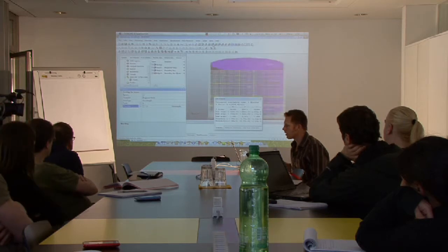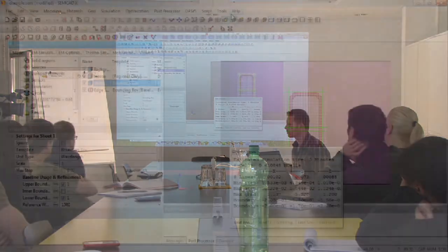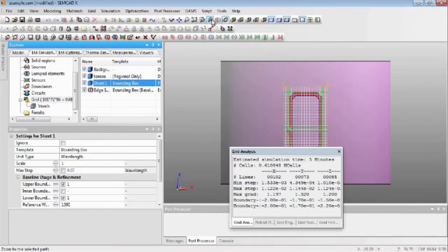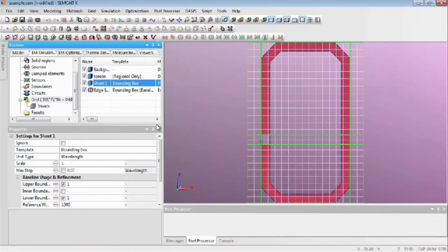And let's have a look now at this specific example. We're going to go back now to our antenna. Let's just zoom in a little bit here. Can close that for now. And I'm going to change the template here to the geometrical mode. And as before, we have these shortcut keys. So using the numerics 1, 2, 3, and 4, we can switch through templates. So I'm using the geometric mode.